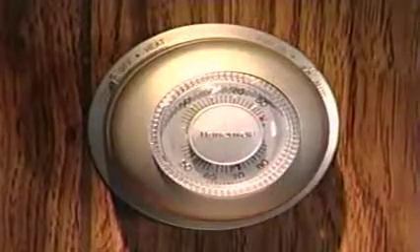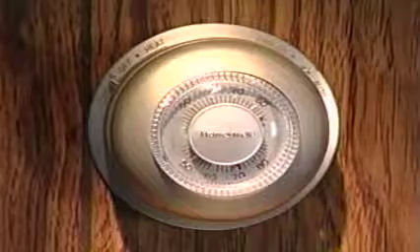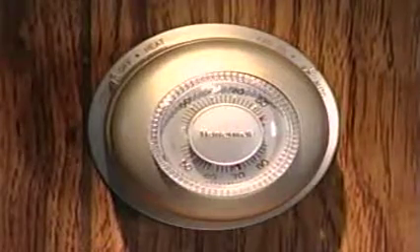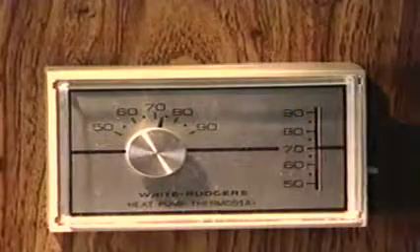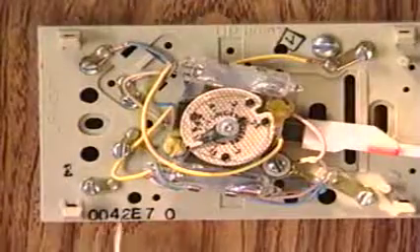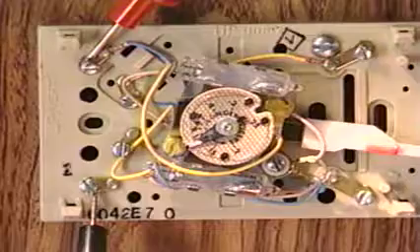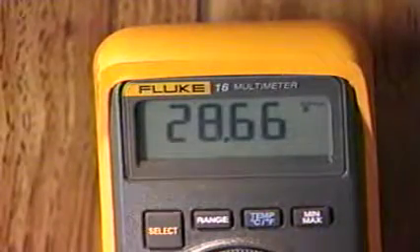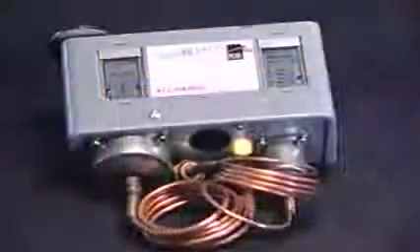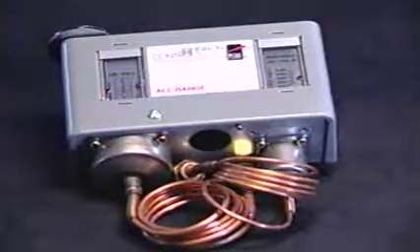Thermostats open and close their contacts depending on the temperature they sense. Thermostats can be remote bulb or bimetal devices. Thermostats can be checked with a voltmeter. The voltage across an open set of contacts should be the same as the circuit voltage. Pressure switches open and close their contacts depending on the system pressures they sense.